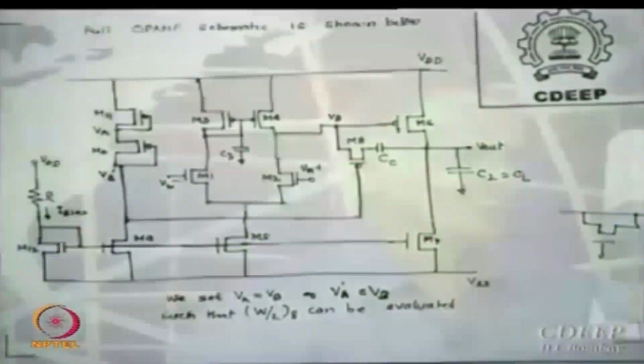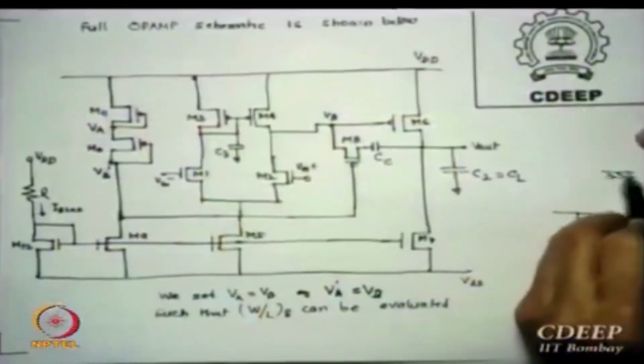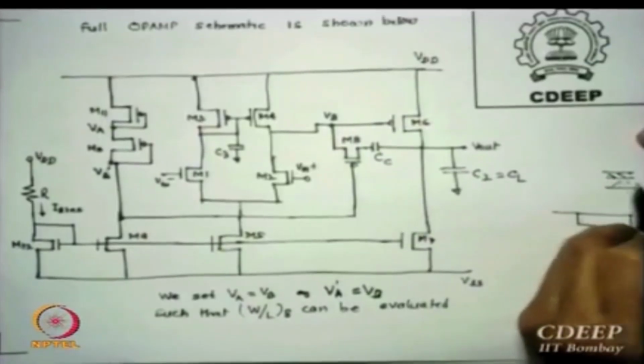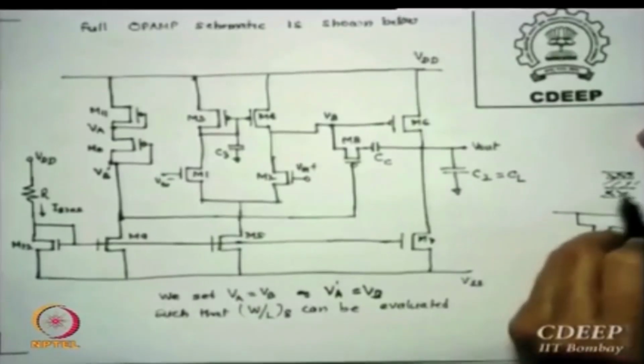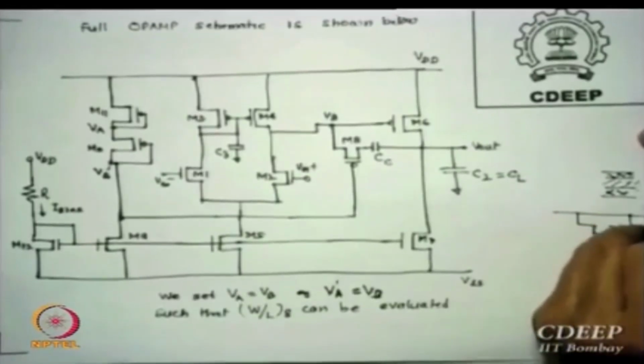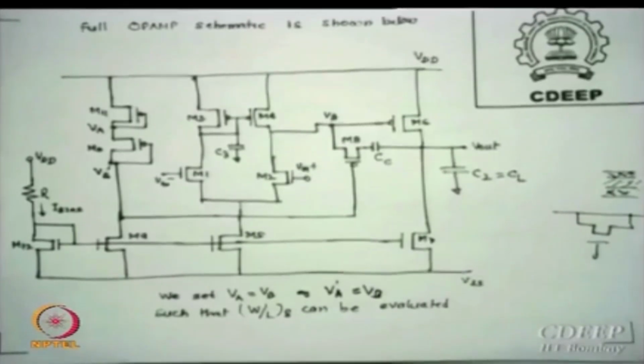So please don't think other capacitors cannot be made, but that is very difficult because you need a technology which is called poly oxide poly, it's called POP. If you have more than one layer of oxides available and a double poly process, then you can create poly oxide poly, okay, or at times metal oxide poly.